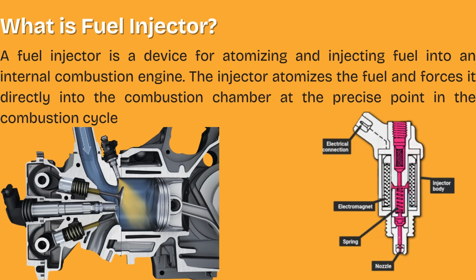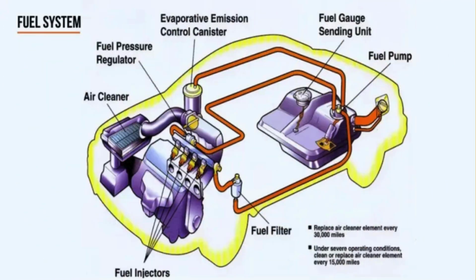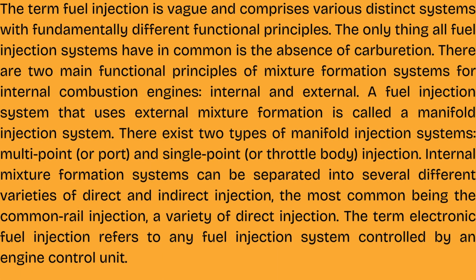What is a fuel injector? A fuel injector is a device for atomizing and injecting fuel into an internal combustion engine. The injector atomizes the fuel and forces it directly into the combustion chamber at the precise point in the combustion cycle. The term fuel injection is vague and comprises various distinct systems with fundamentally different functional principles. The only thing all fuel injection systems have in common is the absence of carburation.